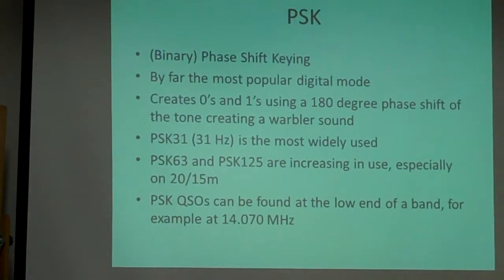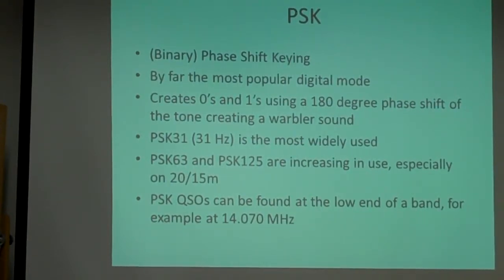So when you're operating PSK, you will get character drops or misprints every once in a while, but it's good for about 95% or greater most of the time. It's really not a major issue or a major irritant. Under good conditions of low QRM, PSK can be very low down in the noise signal-wise, not even coming up off the stub of the meter. Okay, so down minus 30, 40 dB, and you'll still be able to get perfect prints out of it. So the technology works fairly well in practice, given how simplistic it really is.